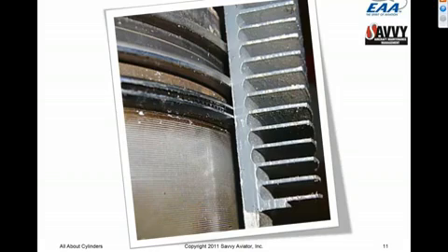As the engine is started and warms up, both the cylinder barrel and the piston expand. But because the piston is made of aluminum and the cylinder barrel is made of steel, and aluminum has twice the temperature expansion coefficient that steel does, the piston develops an increasingly snug fit in the cylinder as the piston and cylinder come up to full operating temperature. And when the engine is actually running, there's a very snug fit between the piston and the cylinder walls, and the rings only have to make up a very tiny gap, a very tiny annulus between the piston and the barrel.